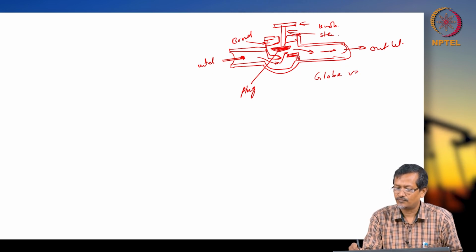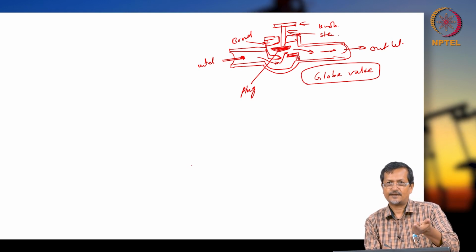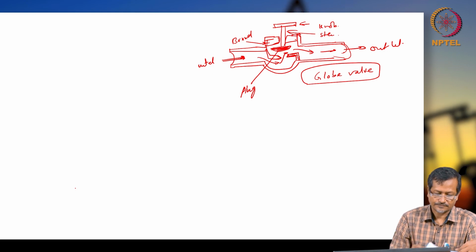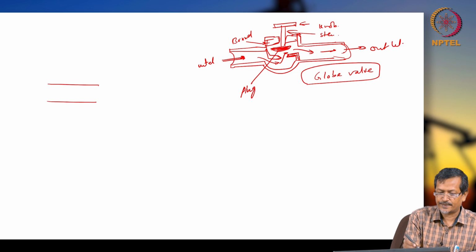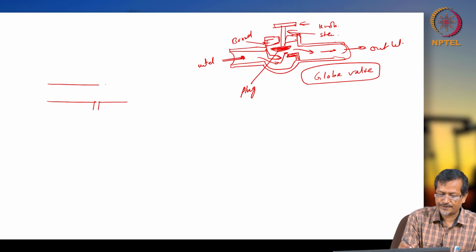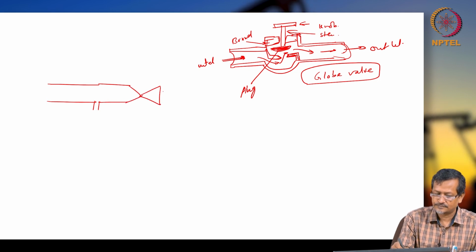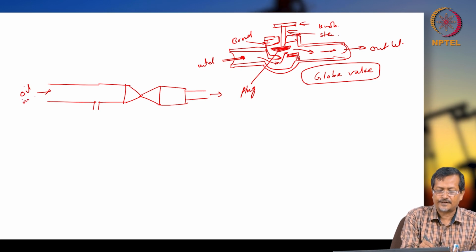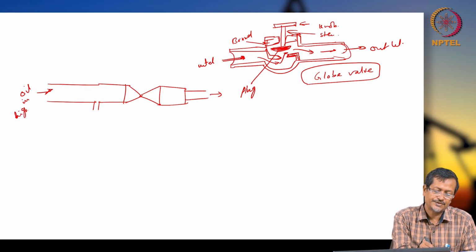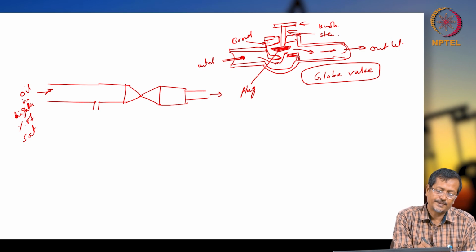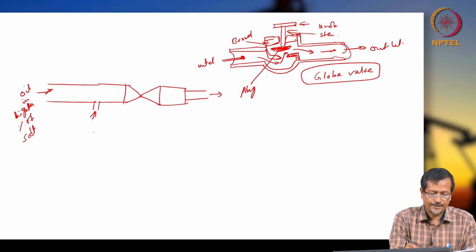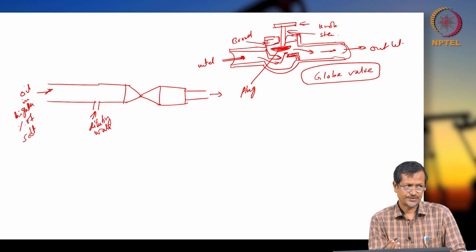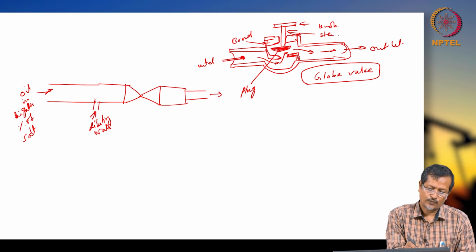So this will be controlling flow, and it will be helping in mixing of oil and fresh water. So how will this fresh water and oil be mixed? Normally there will be one pipe coming like this, then inlet flow will be there. So oil in, oil with a higher percentage of salt will be coming, and there will be diluting water. This diluting water will have a lower salt concentration. Now we are injecting through this, and this diluting water will pass through some nozzles.